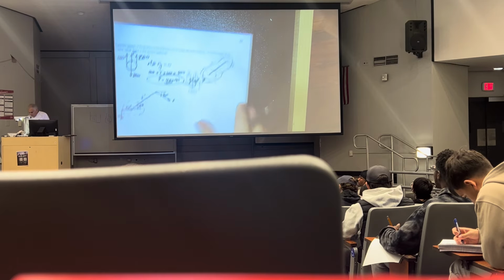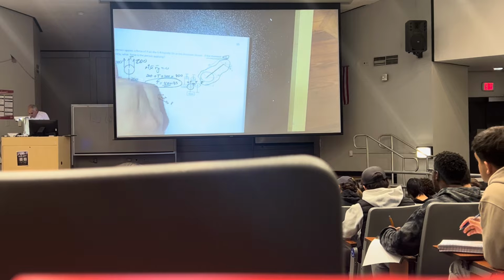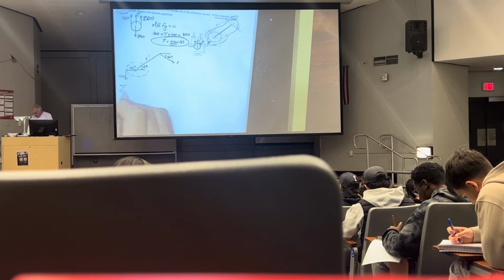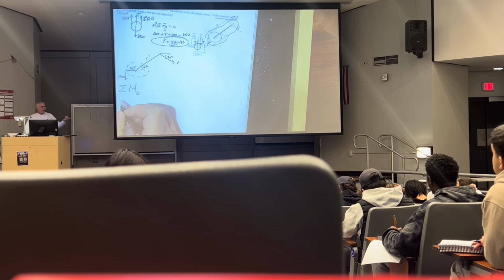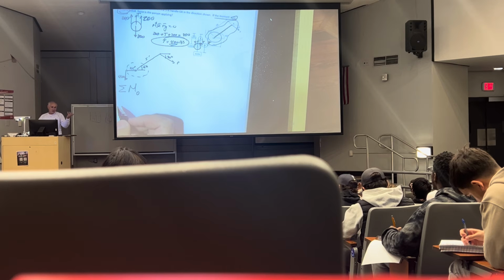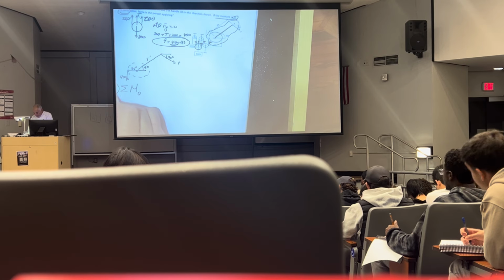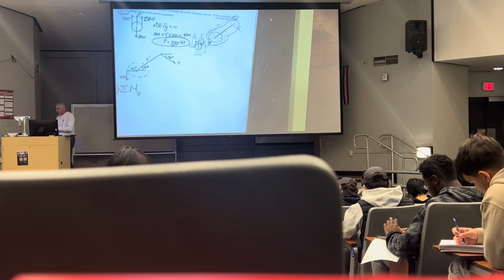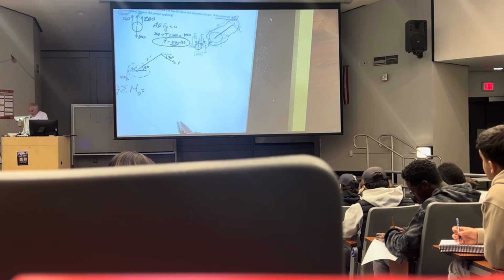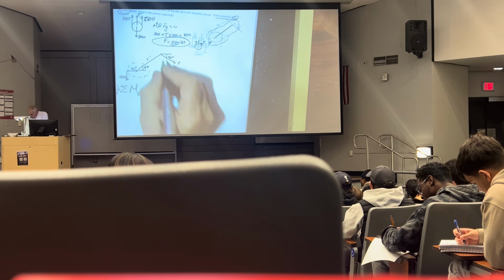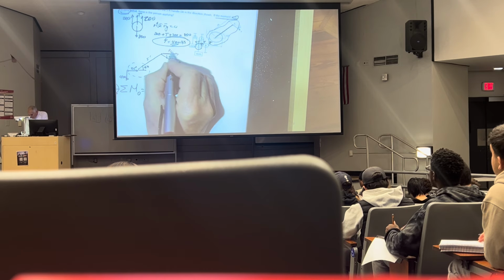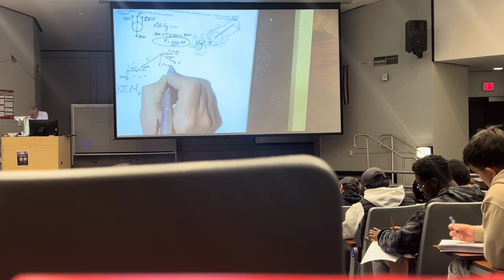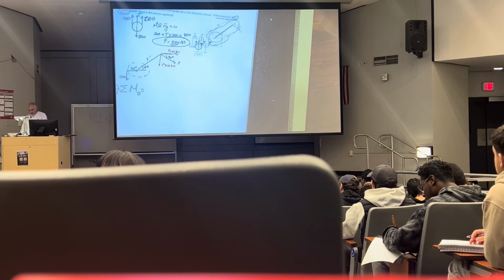It says here, hey, the moment of O is 0. About O. So I'm going to sum moments about O. Can I take clockwise or counterclockwise? Which one? Doesn't matter. I'm going to choose clockwise because I like being opposite to standard, which is counterclockwise. Sum of the moments is equal to, well, what do I got? This guy has a component this way, P cosine 30, and a P sine 30. Yes?